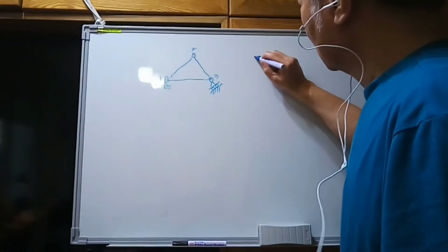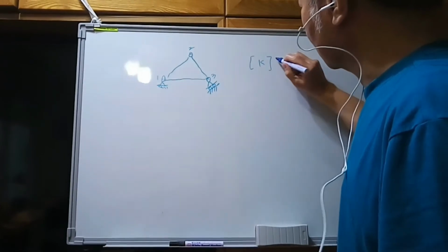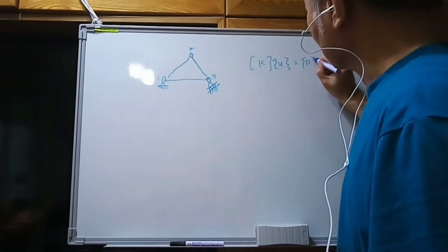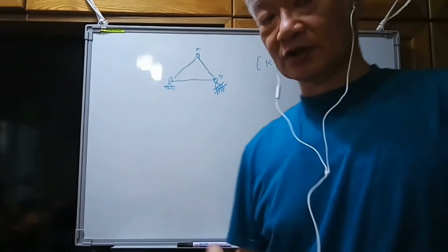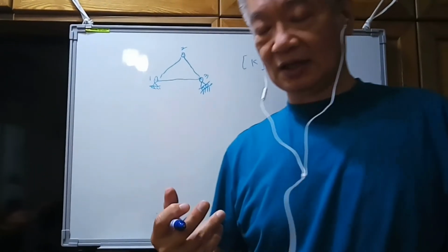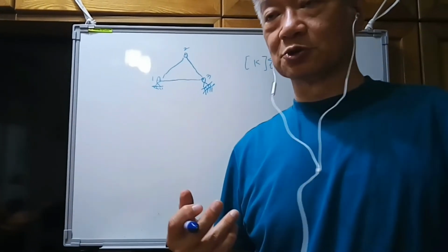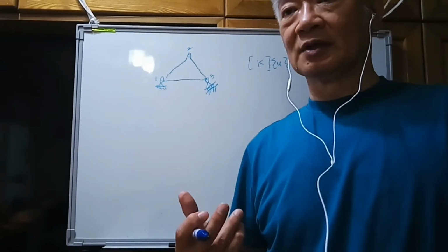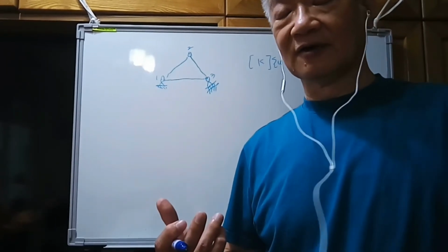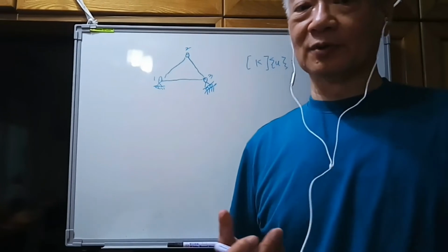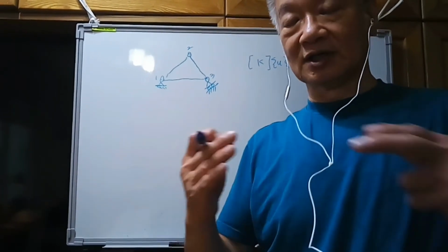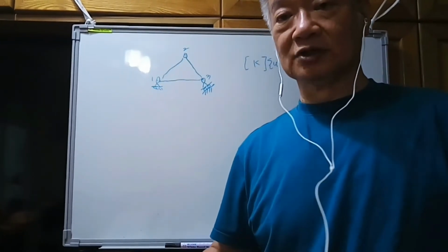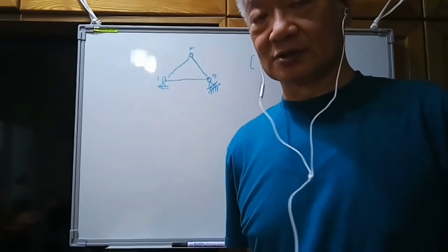we can follow the usual solution steps, the common solution procedure. We will transform the element stiffness matrix to the global component first, and then we can assemble the element stiffness matrix into the global stiffness matrix.